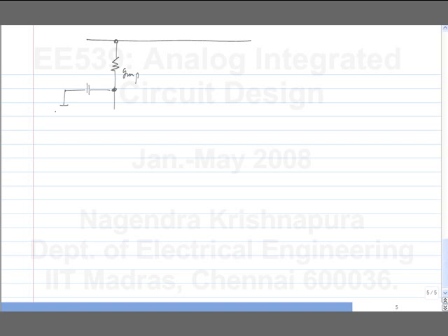This is Cdb,n plus Cdb,p plus 2 times CGSP. And this is also the controlling node for the other transconductor, GMP. The output is terminated in a short circuit, and this is the current I am interested in.